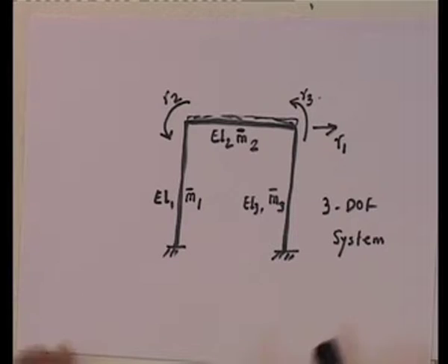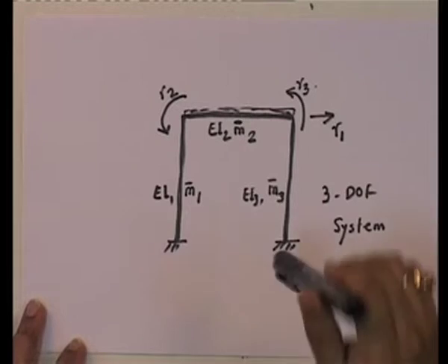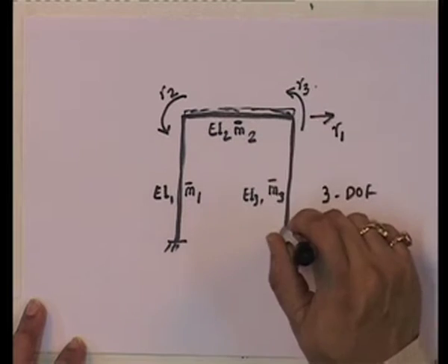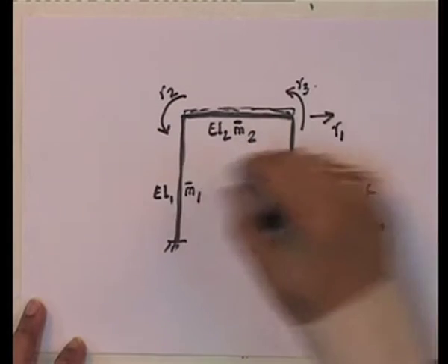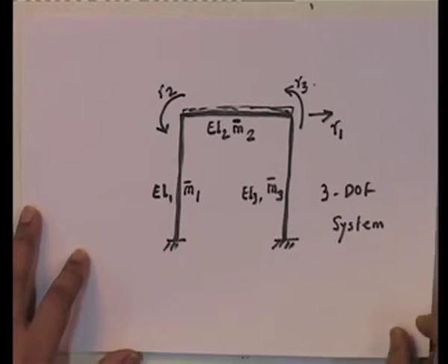Now, just like we did in the classical structural analysis problem, what did we do? We found out the stiffness matrices of each member, and then used these member stiffness matrices to find out the structure stiffness matrix. And what I am going to do here is exactly the same. I am going to first start off by looking at a member and defining it. It is not just a stiffness matrix, you have to define the mass matrix also, and we will see how these are defined.